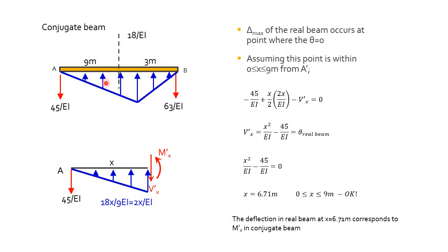Continuing, I know that my maximum deflection would be somewhere between the load and the maximum applied load, like this. If you forgot how it looks, this is your simply supported beam, and you have a load. Usually, if the load is skewed toward the right side or the left side, the maximum deflection is somewhere here, on the left of your support if your support is towards the right side.